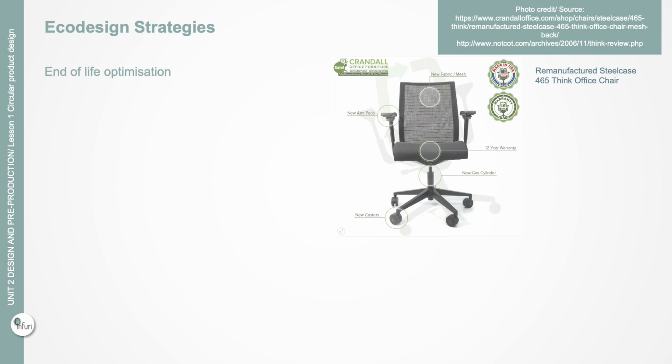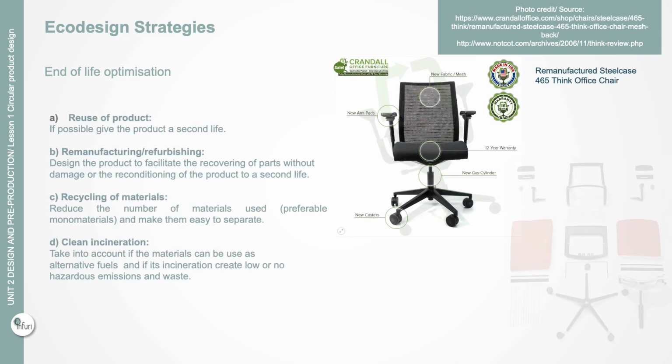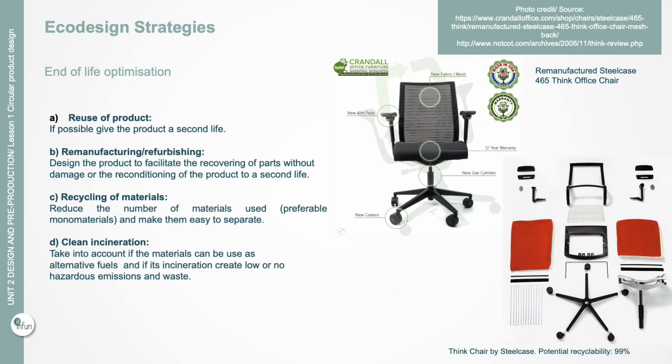To avoid the amount of waste generated, any strategy that facilitates its reuse or the recovery of some of their components is a priority. Also, the possibility of remanufacturing or refurbishing the product should be considered and propitiated. The structural and material simplicity is again a facilitator, and any of the options to ensure the ease of disassembly and reassembly: modular structure, non-permanent unions, etc.